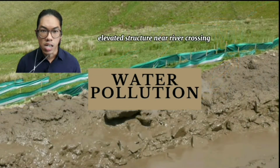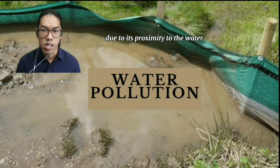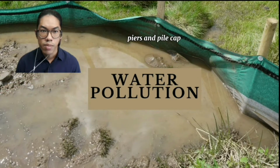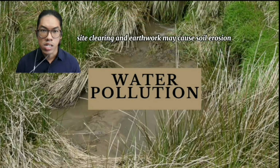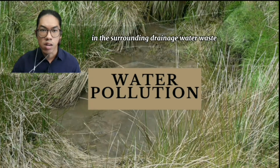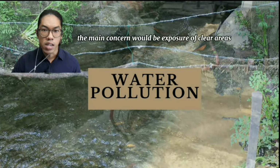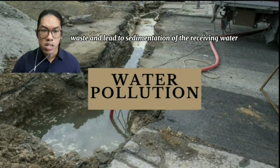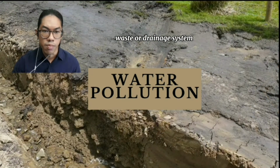Elevated structure near river crossing may result in sedimentation of the river due to its proximity to the water during construction of viaducts, piers and pile cap. Site clearing and earthwork may cause soil erosion and result in sedimentation in the surrounding drainage waterways. The main concern would be exposure of clear areas, as this would increase erosion risk and lead to sedimentation of the receiving waterways or drainage system.